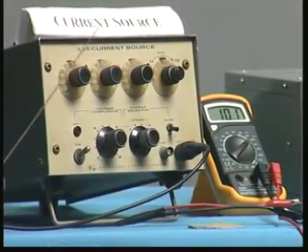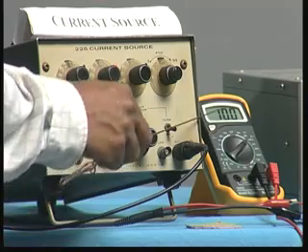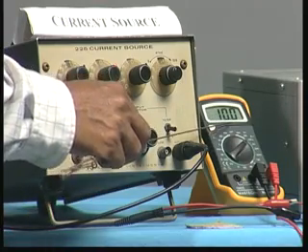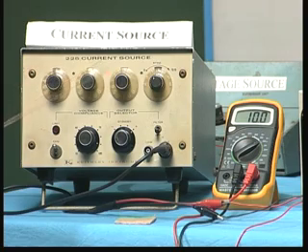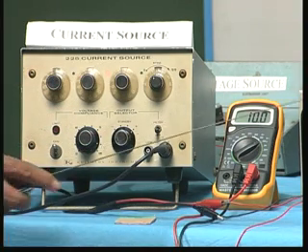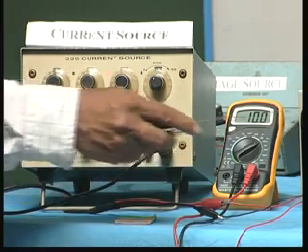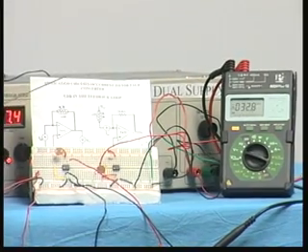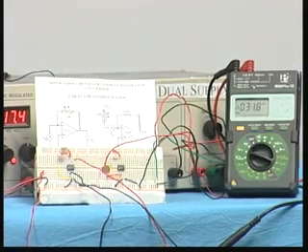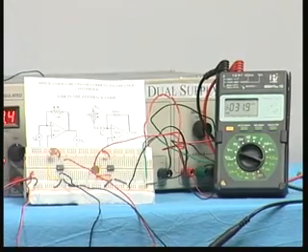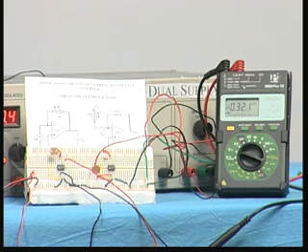Now let me apply the current. The current here is about 10 microamperes as read from the multimeter here. It is 10 microamperes, and here also it is 10 point something, so 10 microamperes. And now please observe what output voltage you are getting. You are getting something around 33.4 millivolts or so, so around 33 or so. Now this corresponds to the current that is generated due to the LDR present here.